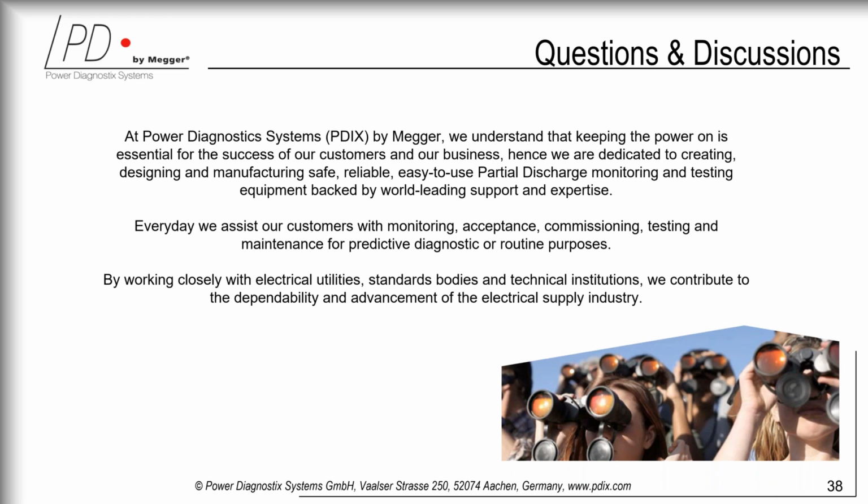Yeah, so at Power Diagnostics, we boast a large variety of instruments, both for offline and online measurements. As you saw Mihai covering monitoring solutions that were primarily installed during construction, as you said. There are also, as you mentioned, the ICM monitor. There is an ICM monitor portable solution that could be used for non-permanent as long as you have your bushing adapter or your coupling units in your termination box that are already pre-installed.